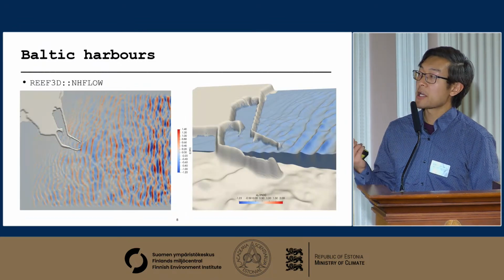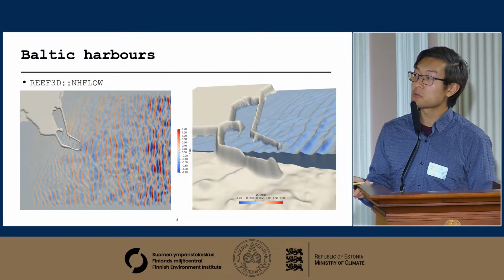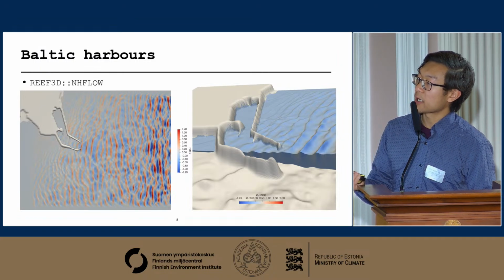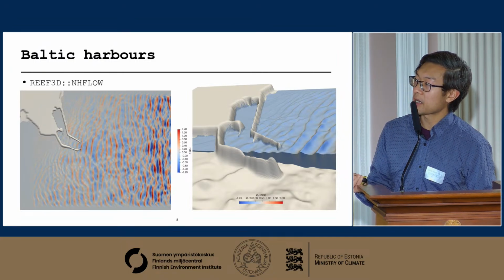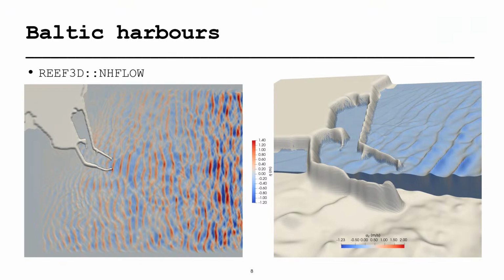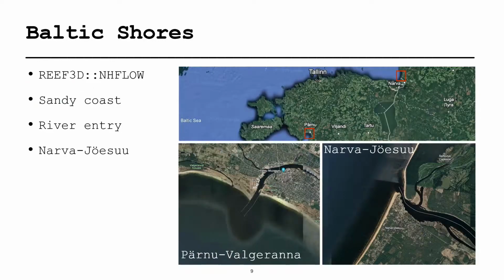But with NHWAVE, we can also reproduce very similar results. That's with NHWAVE now, and it's also a 3D model, so you can look at cross-sections of how the waves propagate towards the coast. If you look at the coastline, you see some whitened areas that indicate wave run-up above the still water level, so we can look at the swash zone dynamics. This might look a bit weird because I stretched it vertically by a factor of 20 just for visualization. So it's not really that the waves are splashing up so high.